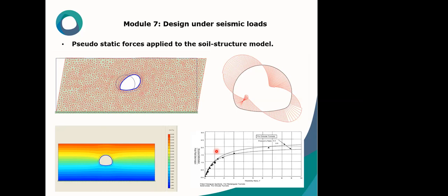Well, pseudostatic force applied to the soil structure model. Earthquake is a dynamic phenomenon, and the most ideal approach to simulate the structure under seismic events is nonlinear, fully dynamic analysis. Yeah, we know nonlinear, fully dynamic analysis is the best approach.